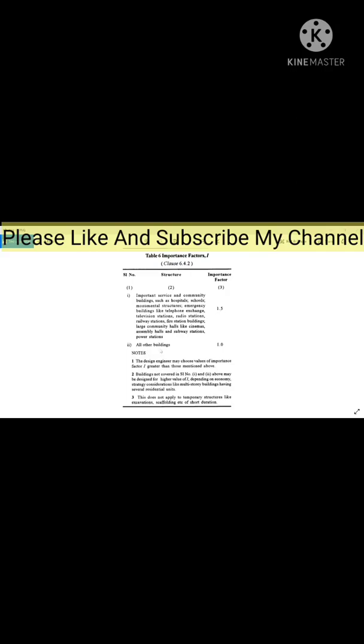All other buildings, residential or unimportant buildings, are also important, but the capacity of the building, or how many people that building carries, also matters. Hospitals you can consider as important structures. For all other buildings, we have to consider the factor 1. This is given by the IS code, so we are not going to consider anything by our own mindset. We consider according to the IS code.